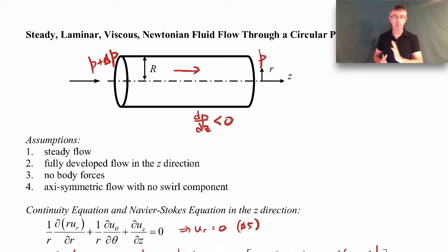So you have to keep pushing it to overcome those viscous effects. If it was inviscid, so if there were no viscous effects, I could just tap on one side of the fluid and it would just keep propagating through the pipe. Nothing would slow it down. But because it's viscous, we have to constantly keep pushing on it. And so we have to apply some pressure on that side, a little extra pressure, delta P, so that we can push the fluid along.